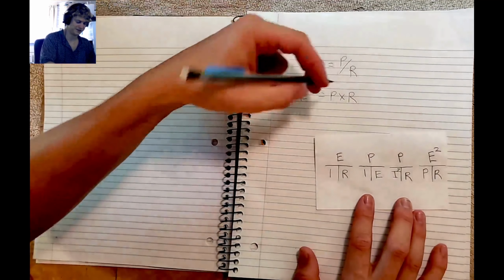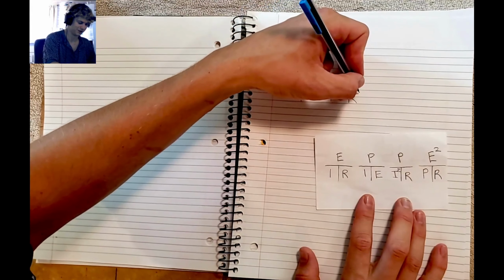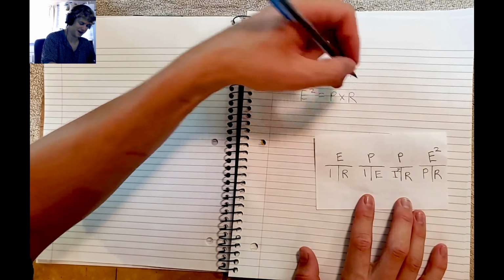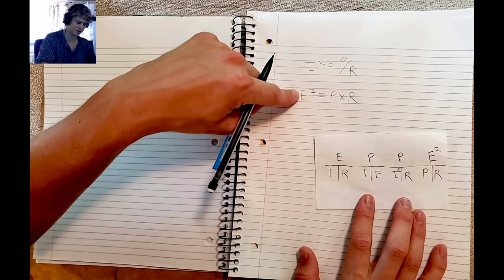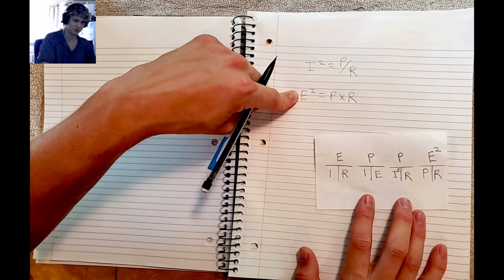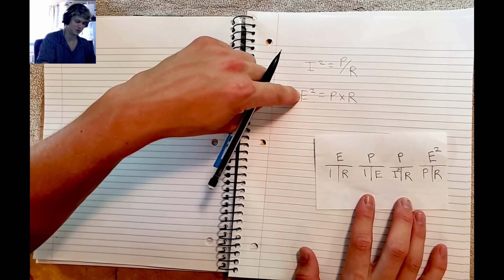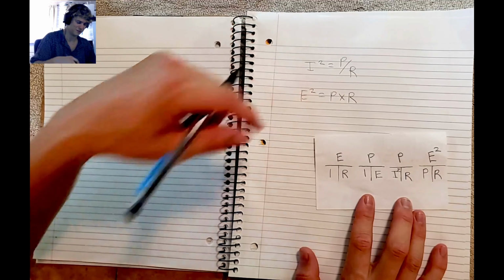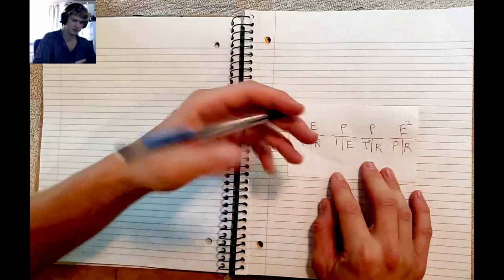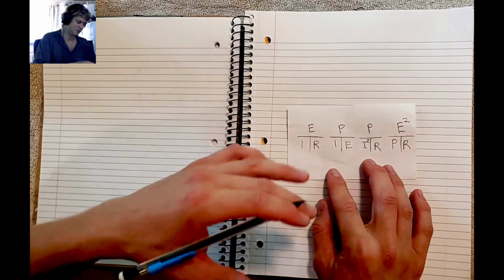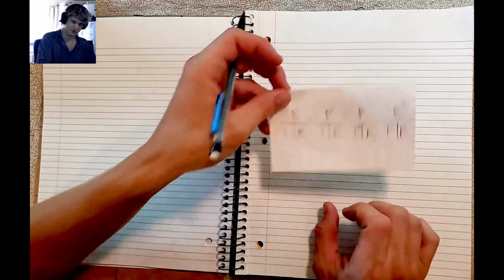So basically the same thing. All that it's saying is that when I multiply P times R, that number is going to equal something that's squared. So for this number to be squared, we have to square root it when we actually want to find our answer. So E squared equals P times R, therefore P times R, that total number is going to be square rooted to create this E squared number. Okay, so you could always write each of these down in the beginning, and then any time that you want to use it for any of these problems, you can just pull out this flashcard.